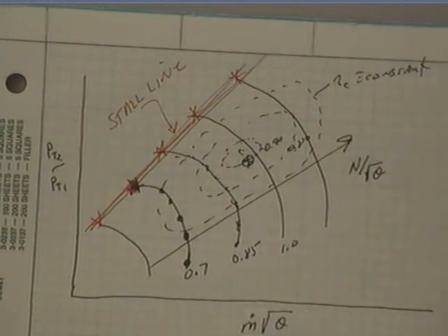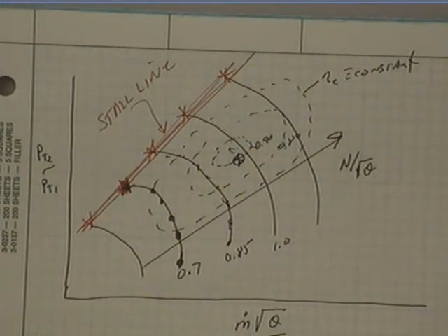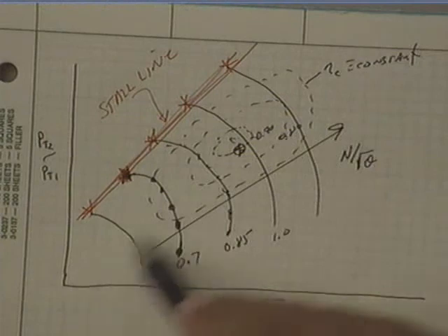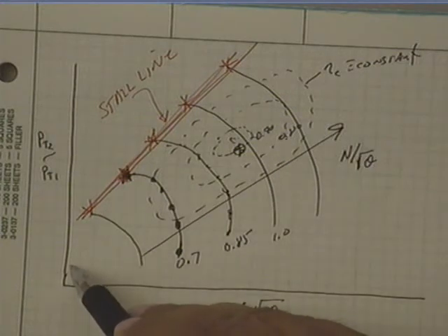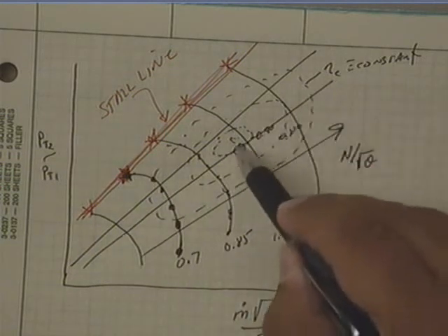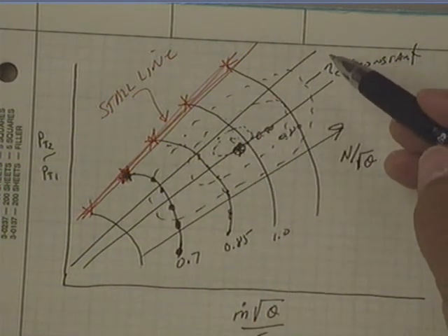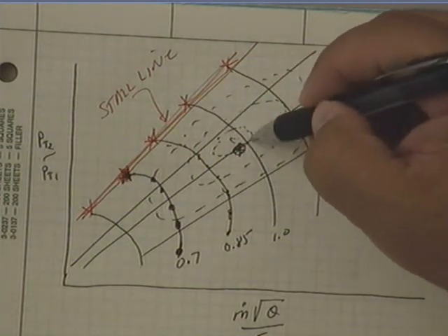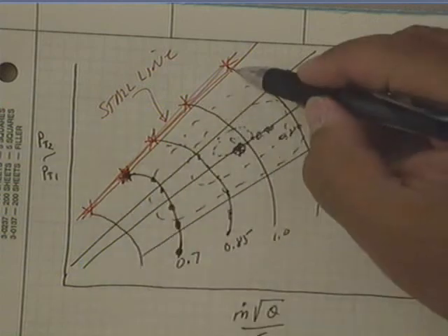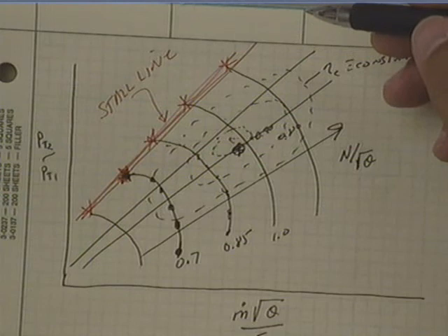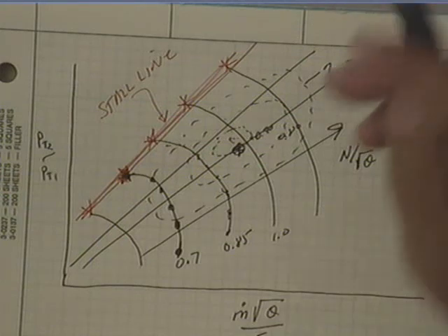Now, when you operate a jet engine with an axial flow compressor and you just push the throttle forward, you're going to move along an operating line that's somewhere here or somewhere like this, right? Where at some point you're going to go through your design point. Okay. Now, it's the relative distance between your operating line and this stall line that we end up defining as stall margin. Okay.